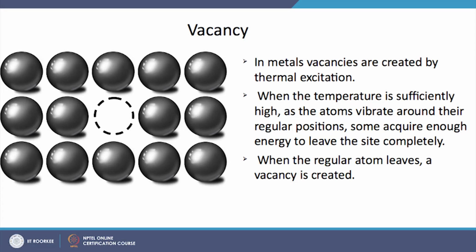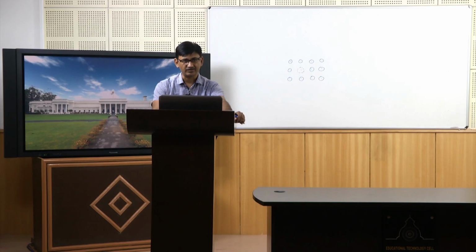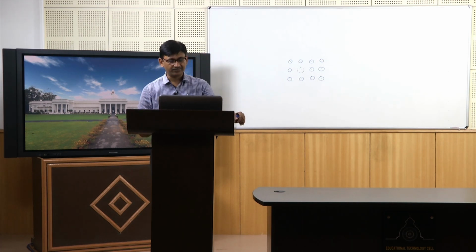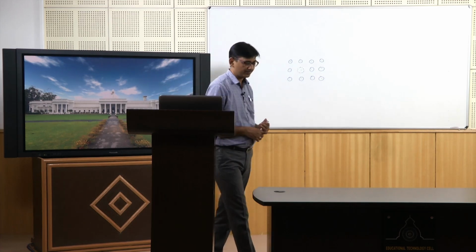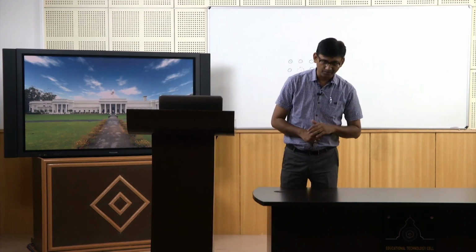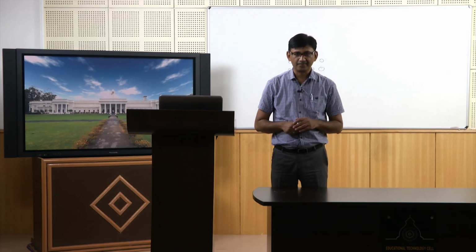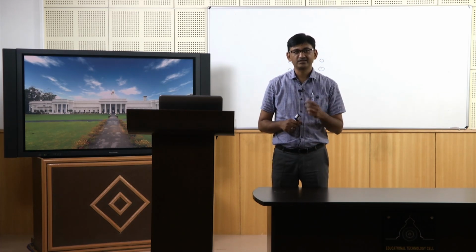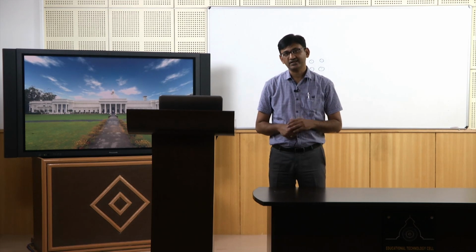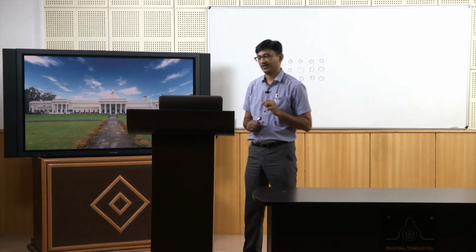So, this is actually a temperature dependent phenomenon. When the temperature is sufficient and the atoms vibrate, sometimes they acquire sufficient energy to break free, and when they do that, it is called a vacancy. Now, the most important quality of this defect, which is called vacancy, is that this is a thermodynamic defect. This is the only defect which is a thermodynamic defect.